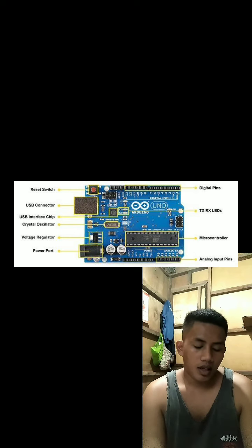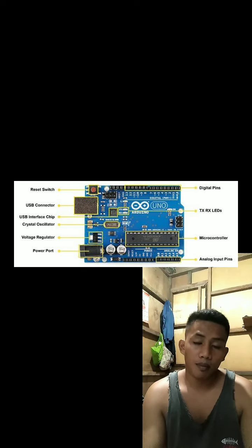So 16, AREF. AREF stands for analog reference. It is sometimes used to set an external reference voltage between 0 and 5 volts as the upper limit for the analog input pins.